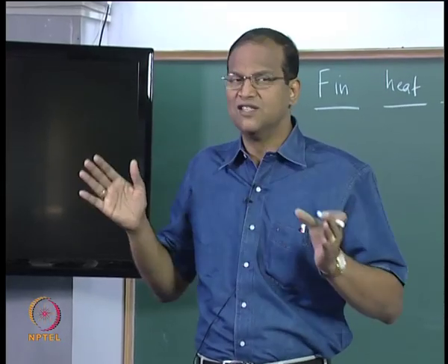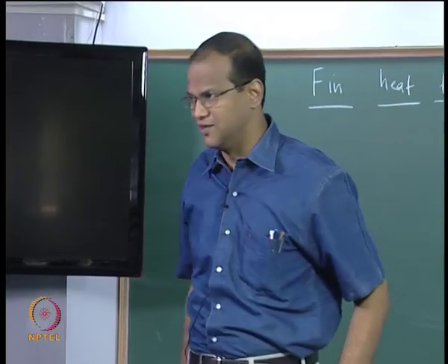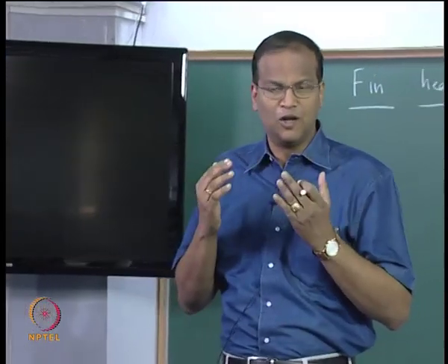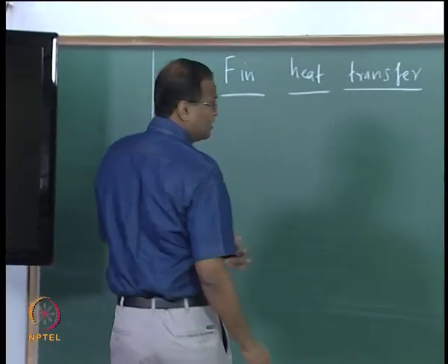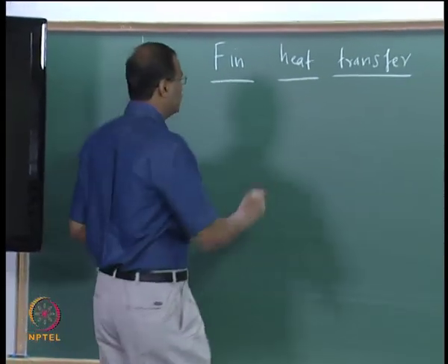So, in the context of these three objectives, now if you want to increase heat transfer, basically we are talking about increasing convective heat transfer. So, the governing equation is basically the rate equation, the Newton's law of cooling, Q is equal to